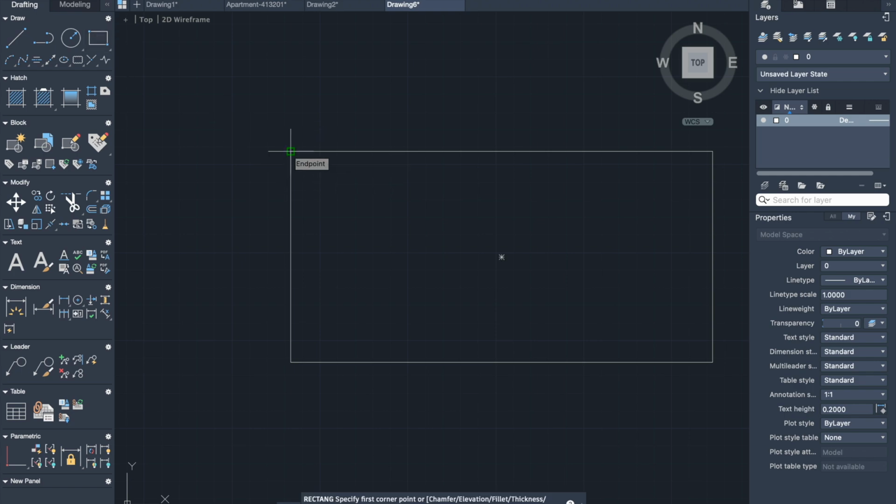To go on from here, basic exercise, we can create a spare bedroom or a washroom off to the side here or something. Now, a couple things that I'd like to show how to do. If we use our line tool here, we can select our point, and then we can come out. Now, if we hold down the shift key, this will keep us linear or orthogonal.